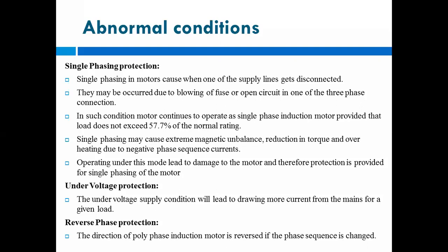Then in such conditions, the motor continues to operate as a single phase induction motor provided that the load does not exceed 57.7% of the normal rating. But its load carrying capacity decreases. Whatever the rated capacity given, now the motor can carry only 57.7% of the load.